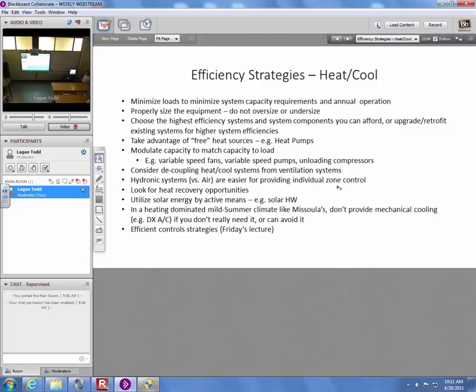Right. What I'm talking about more is motorized dampers that are controlled, which you don't tend to see in any residential system usually. This is a commercial world thing that is unlikely to make its way into the residential system. It turns out the computer room is way too hot, so you modulate a damper down, neck it, close it off.